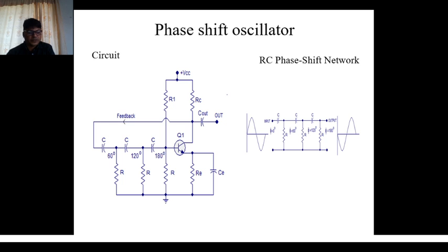Hence, in the phase shift oscillator circuit, the voltage divider R1 and R2 provides DC emitter-base bias. Also RC controls the collector voltage, and RE and CE provide temperature stabilization and prevent AC signal degeneration. The oscillator's output voltage is coupled to the load by the capacitor C out.